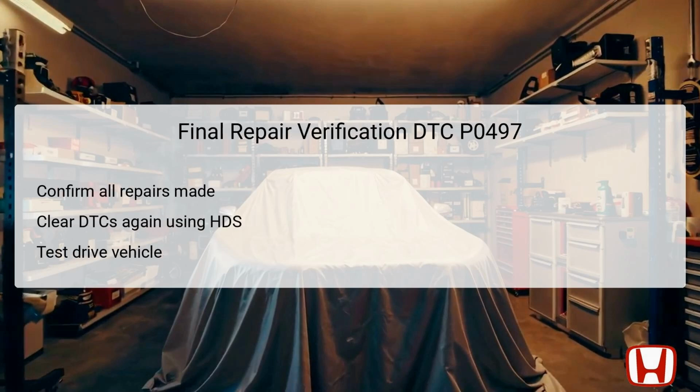To conclude the troubleshooting and repair process for DTC P0497, conduct a final verification of all repairs made. Confirm that any components replaced or repaired are properly installed and functioning as intended. Clear the DTCs again using the HDS to reset the system and eliminate any previous fault indicators.